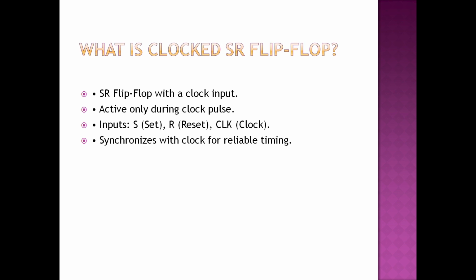What is a clocked SR flip-flop? A clocked SR (set-reset) flip-flop is a version of the SR flip-flop that includes a clock input. It only responds to the set and reset inputs when the clock signal is active. Typically, the clock is 1. The clock mechanism ensures that the flip-flop operates in synchronization with other components in a digital system.